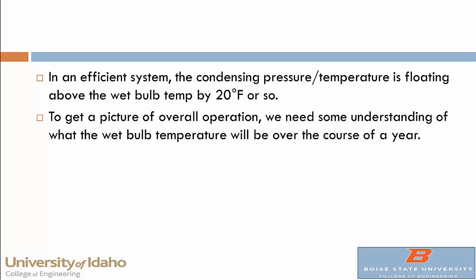It should be obvious, but let's talk about this. The conditions around a condenser are constantly changing because it's the outside air, right? So sometimes it's warmer, sometimes it's cooler. If we have the evaporation going on, we can actually drive it below the temperature of the outside air. And as we talked about in the last lecture, the amount of heat that gets rejected is dependent on the outside air temperature and the difference between that and the temperature in the refrigerant and the amount of air that's flowing through it and that sort of thing.